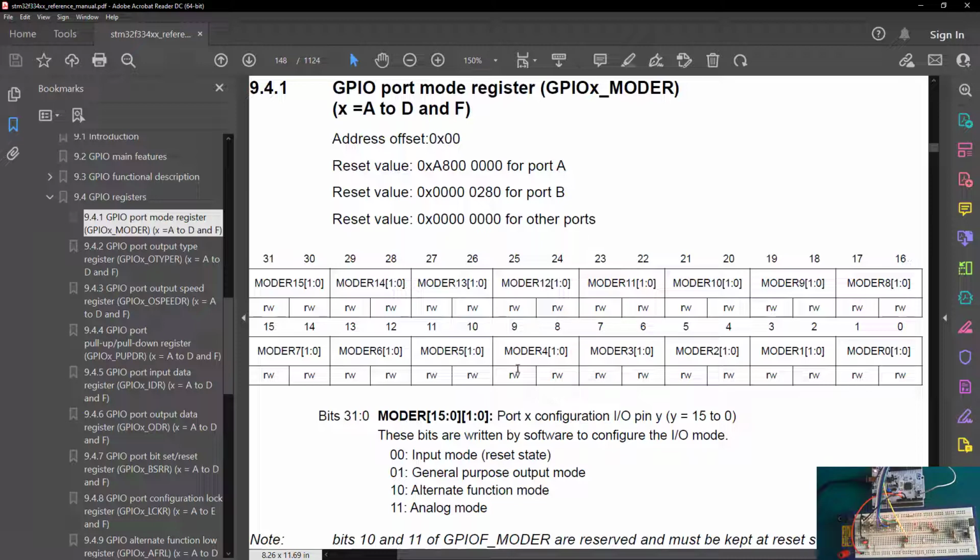Right? Now, if we want to write GPIO PA4 as an output, that means we only need to change bit 8 here. Bit 9 is going to remain 0, and bit 8 here is going to now turn to 1. That will then mean 01 introduces the GPIO port A pins. And we're going to do the same on all of these pins. And this will mean for PA8, we then need to write a 1 onto bit 16 and leave bit 17 a 0. And that will set it into output mode. So that's what we need to write into our code here.